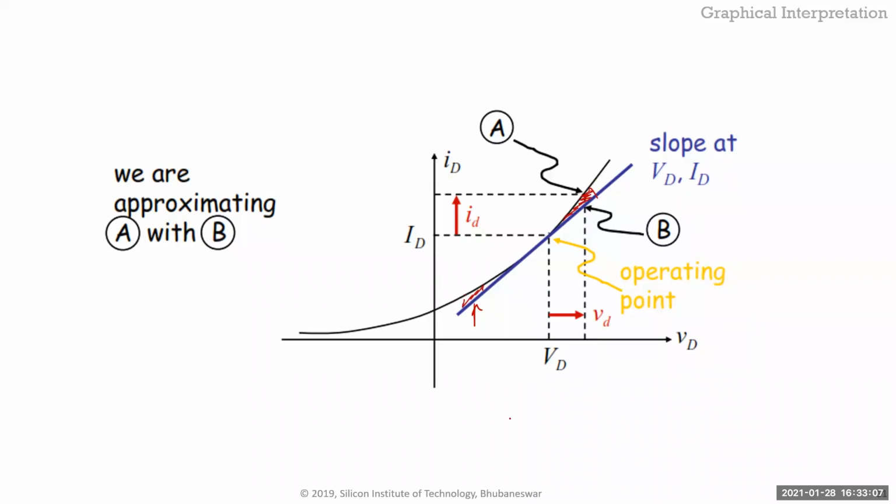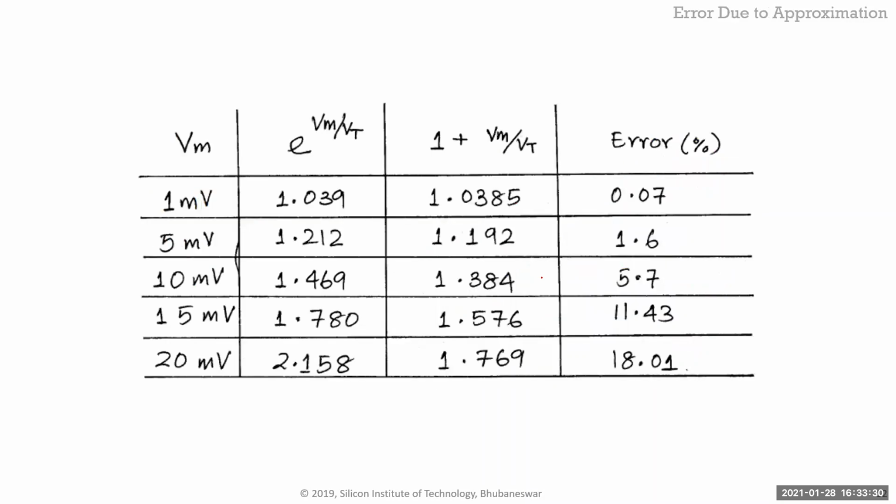Like I kept asking you, 1 millivolt, you said 40 millivolt, then 100, 1,600. But once you go to 1,600, your error grows. And obviously, you don't get to 660 volts or 16 volts. You just clip at your VDD. In GATE, probably you have to write 160, otherwise they'll give you a 0, but in reality, that's not true.